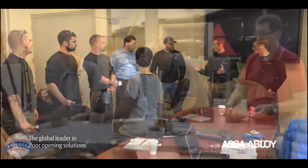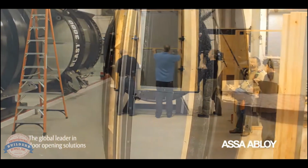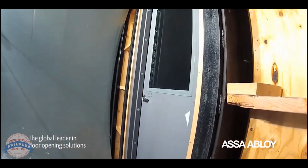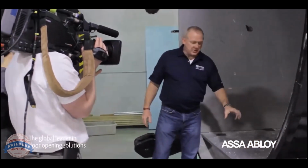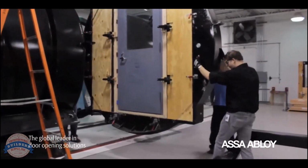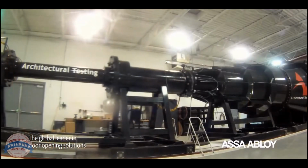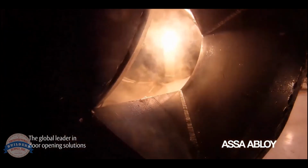Team members from ASSA ABLOY joined forces with Architectural Testing Inc. and the Discovery Channel to demonstrate the strength of these products. The Discovery Channel filmed the demonstration, which aired on the Daily Planet, a show that features interesting accomplishments in science news. The ATI facility houses an indoor shock tube that evaluates the resistance of an opening against a bomb blast. Pressures during the test may exceed 1,700 pounds per square foot. This simulates a blast of approximately 50 pounds of TNT at 86 feet from the door opening.